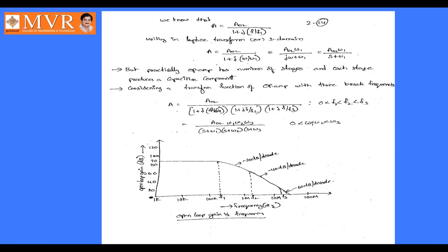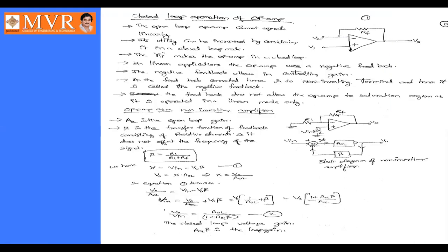You can observe the amplitude of the output signal change when the frequency changes, without changing the input amplitude. This is the effect of the capacitance values in an operational amplifier. This is how we obtain the frequency response for an operational amplifier.